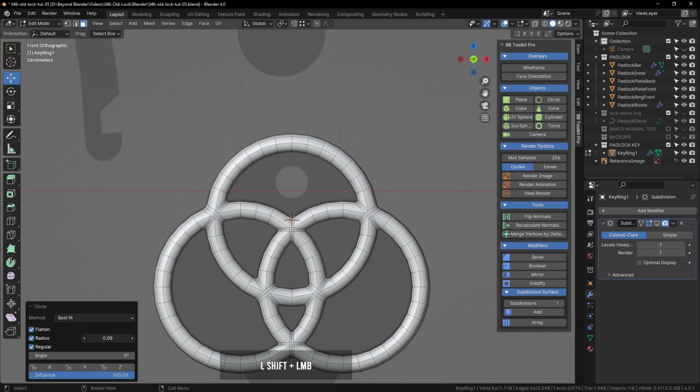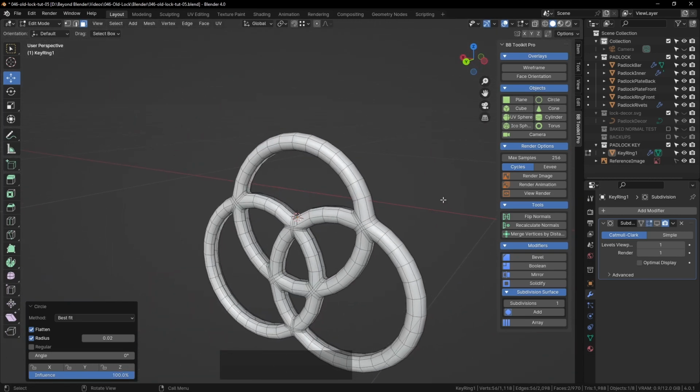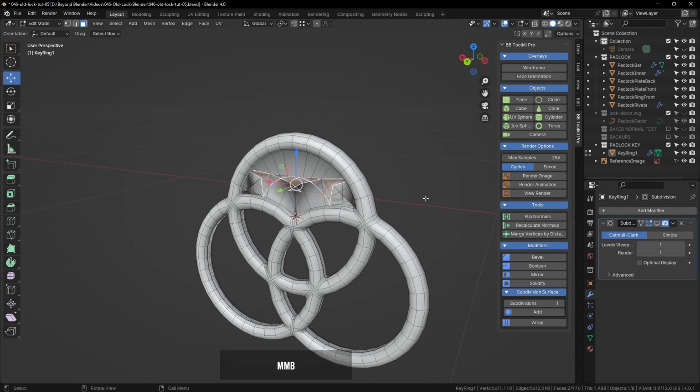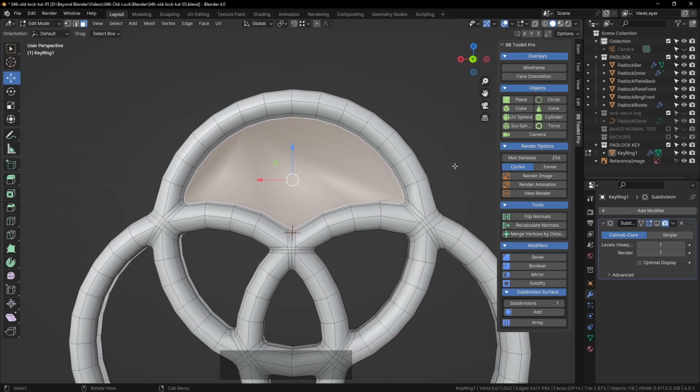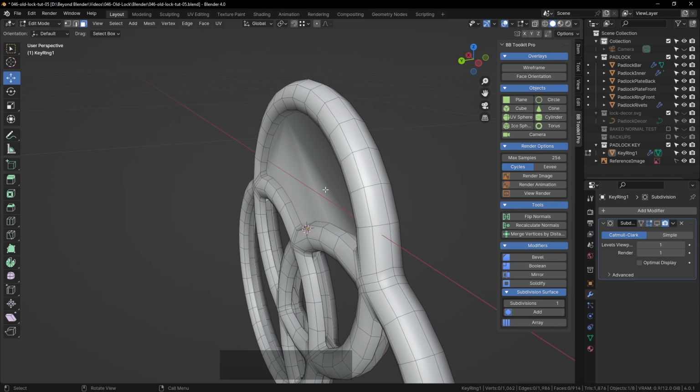So I'm just trying to see what happens here if I change some of these options down there. Maybe one will save me a lot of time. We'll see. Unfortunately, I've not been so lucky this time. So, yeah, that's not... In fact, I can't even see anything. So I'm going to undo that. Back to these filled n-gons. So I'm going to press the I key and give it a very small inset.